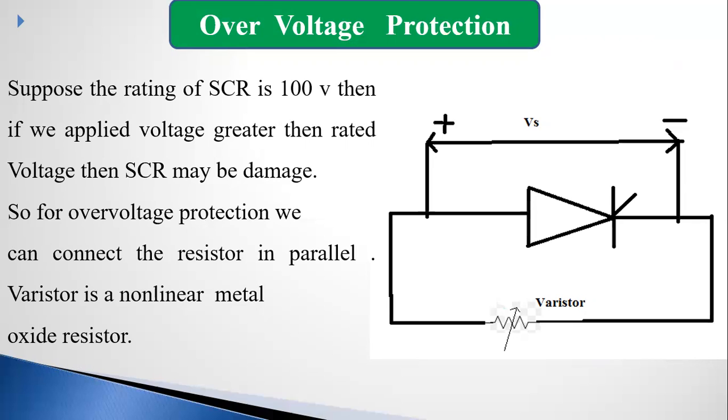For over voltage protection, we can connect a non-linear metal oxide resistor in parallel with the Thyristor.